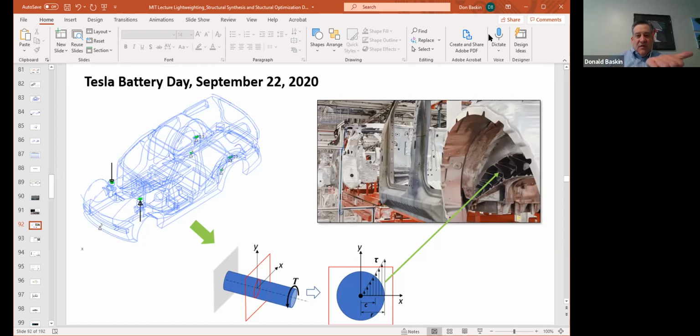So if you have a flat piece of metal that's under a bending load, remember I showed you that equation, the 12 MC over BH cubed. So the H is the thickness of that sheet of material. Well, with most cars, the floor pan is just a very wimpy little sheet of metal. It may only be a millimeter or a millimeter and a half thick. And you consider that your H, that millimeter and a half. And all of a sudden you see it's really not very stiff in bending. Car companies go through all kinds of gyrations to try to make that stiffer, because if it's not stiff enough, it actually starts to make sound. It's only semi-structural when you have that.